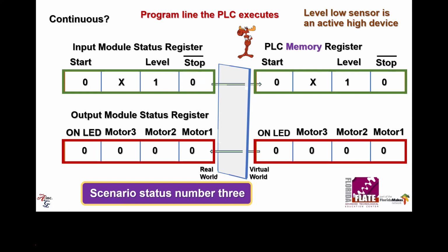There's a 0 there. The signal is low. What does that tell you? It has to tell you that this stop idea, which is an active low button, must be active. That's why there's a low. So what does that mean? It means that there's a stop there. Somebody has pushed the stop button. It's holding the stop button in, at least.